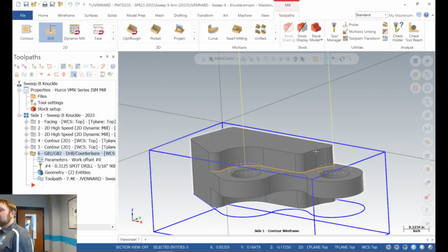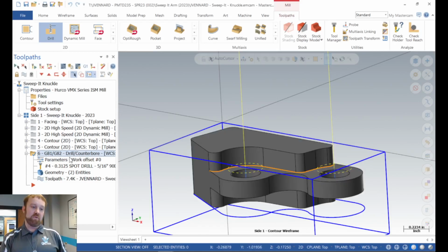Now let's say you're on a situation where you're trying to shave every extra move and every little bit out of the program. If you go to Index and you look at some of their machines, I mean, 25 thousandths clearance is about the most they have for every movement. Like that clearance is clearance. You know, as long as it's off the part and out of the way, there's none of this 2-inch retract stuff. If that was a situation here where the rapid move is more than I want it to be, well, I can bring that clearance height down to basically wherever I want it to be without it taking out that corner of the part. Like literally, and I don't want you to do it, but I want to show you.